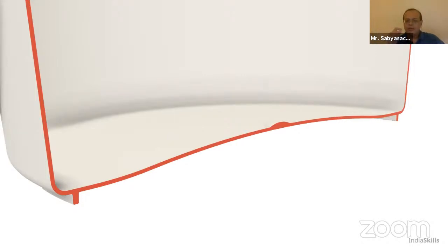We have a rib so that when you fill the bucket up and you want to shift it, most people will not lift it and put it down. They will push it. So what happens is that the entire surface is rubbed against the floor. Imagine if there was no rib running around, then your entire bottom will start getting scraped. That's not such a good idea.